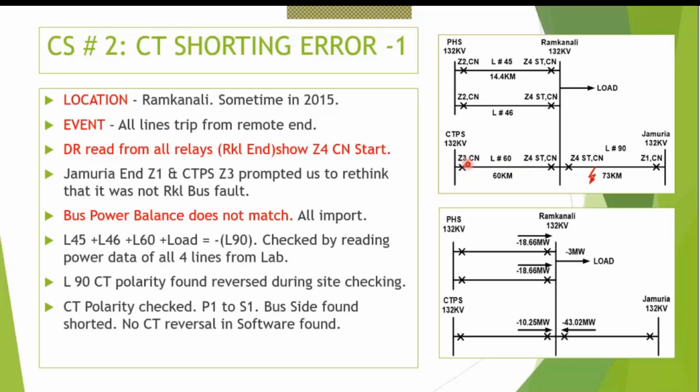The zone 2 of this relay should cover this fault, but because the infeed is more, this impedance is getting multiplied, so the relay does not see the fault over here, this particular relay. This relay sees the fault a little bit more, but still within its zone 2. But since this is a 14 kilometer line, the fault currents fed by these lines are more.